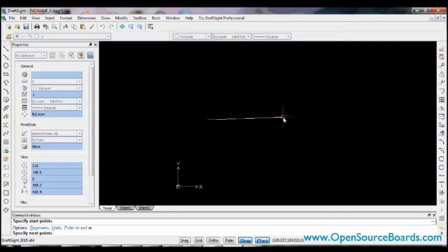So what I'm going to do is go down to my command window, and I actually don't have to click on it. If I just start typing, it'll start typing there. And I'm going to specify my next point. So we're in an XY coordinate system, and we want a relative coordinate to where we currently are. Since we've placed ourselves randomly in space, we don't know our exact coordinates, so we can't give absolute coordinates. What we can do is give relative coordinates, and basically what that means is let's go this distance in X and this distance in Y from this point.